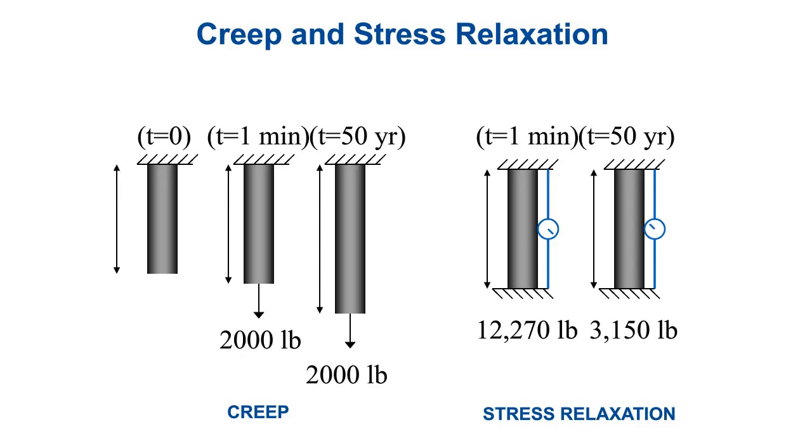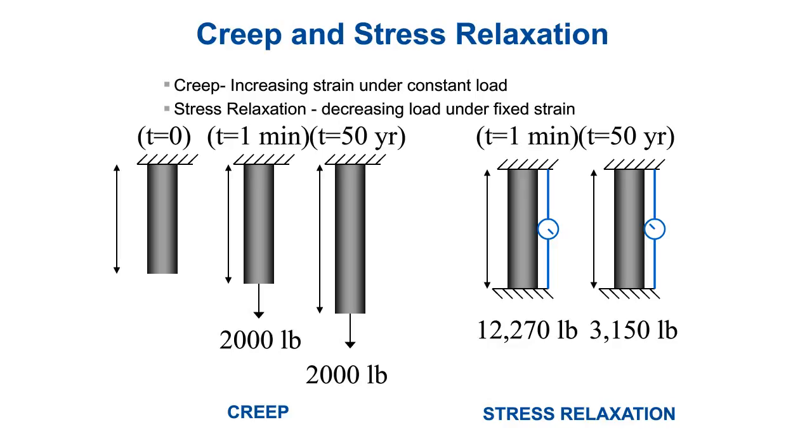Just to give you an understanding of HDPE, some of the characteristics are creep and stress relaxation. Typically, this pictorial here shows you that if we were to apply a strain or force to the material, it will react by elongating and trying to counteract those stresses. So in this particular instance, over a long period of time, the material will compensate by stretching out to try to alleviate the stresses applied to it.